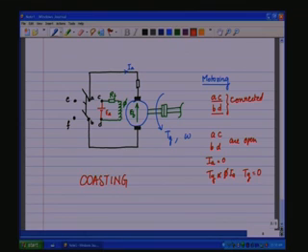The mechanical speed, the omega, will gradually come to 0. Now, if the inertia of the mechanical system, whatever is connected as a mechanical load, is very high, then it can take quite a long time for it to coast down to 0. So, what can be done?